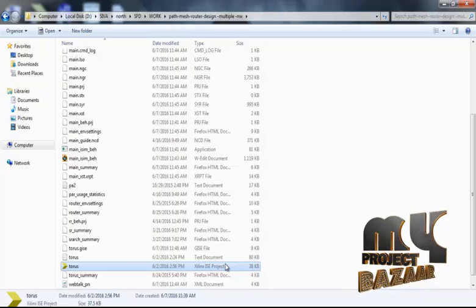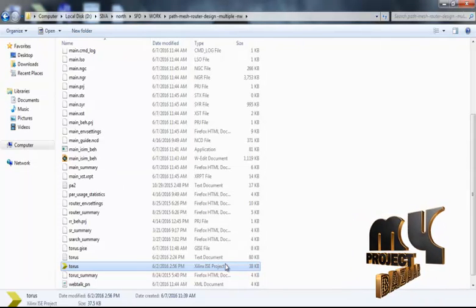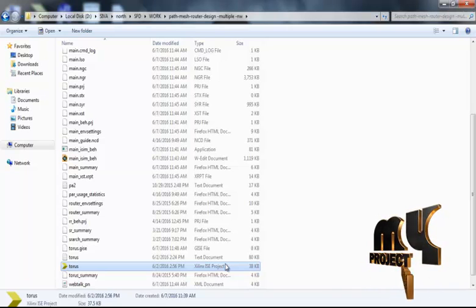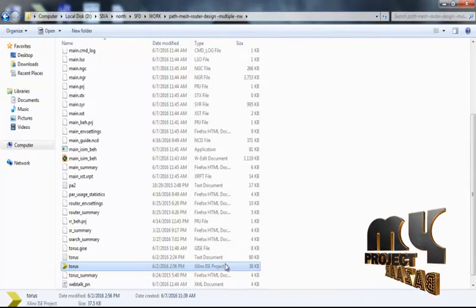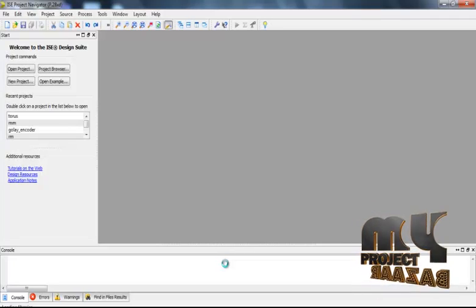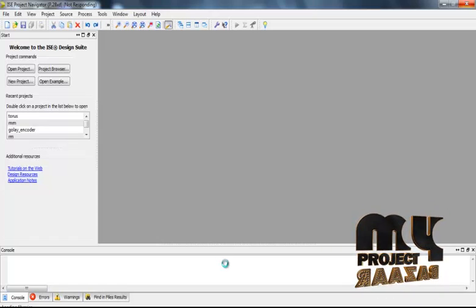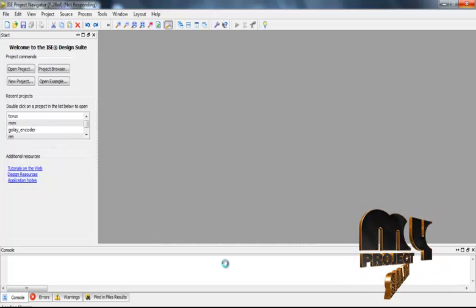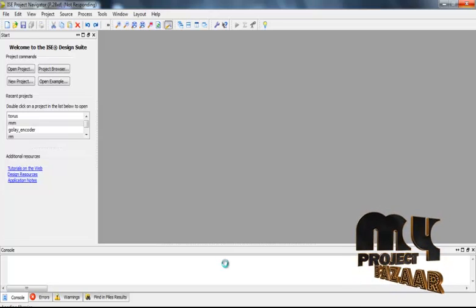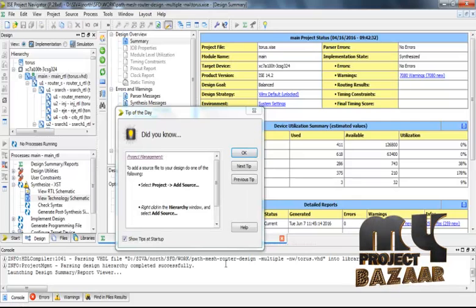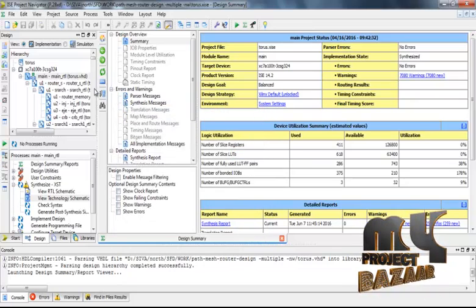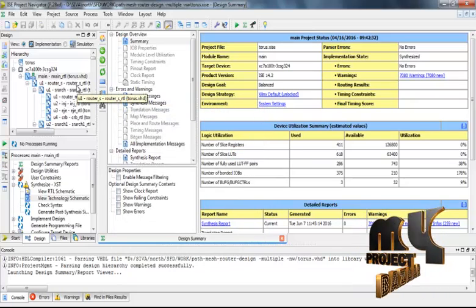And we implement the overall 3x3, 9 router architecture for each 2D mesh topology connectivity, and we implement 4 kinds of 3x3 router architecture, and this kind of communication is mainly based on the off-chip communication. This off-chip communication is used for the gateway connection. The on-chip communication is mainly used for the internal router architecture and the topology based connectivity. These are the final designs for our overall main architecture.